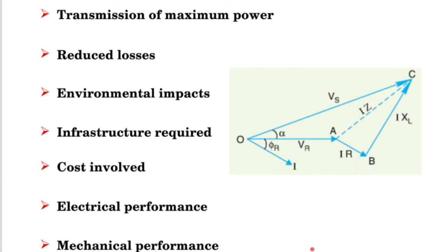Also, in some places, in very difficult situations like cold winter, ice can get deposited on the conductor surface as well. That will make the conductor even heavier on top of its own weight. So when we design the mechanical aspects of a transmission line, we need to consider all these.